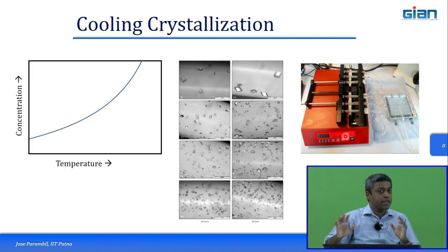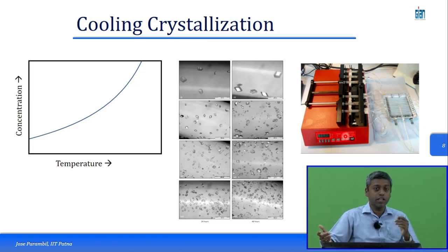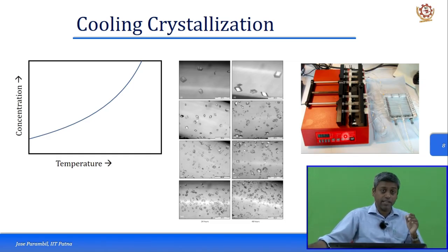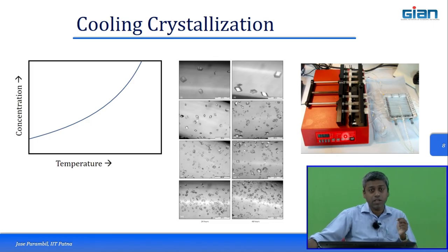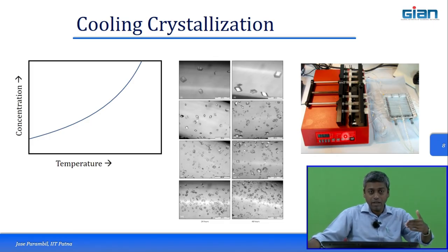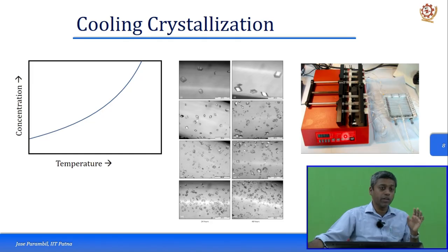So even operationally, you're giving the same flow rate, but when you change the type of pump, the shear rate at which it is being pumped might affect your crystallization, and this is one of the major challenges with respect to protein crystallization. In some cases it might be good, because increasing the shear to a level might increase crystallization, but beyond that threshold, there is trouble. So there is a process optimization that you have to do in this sort of setup.